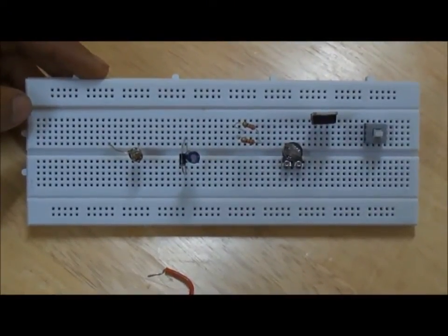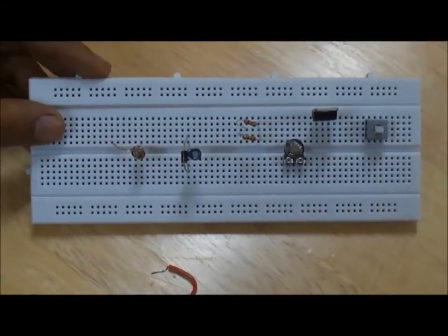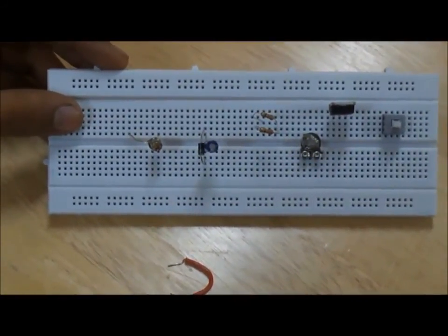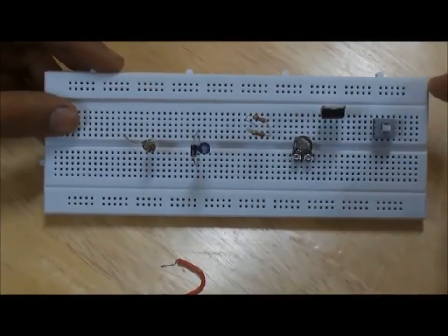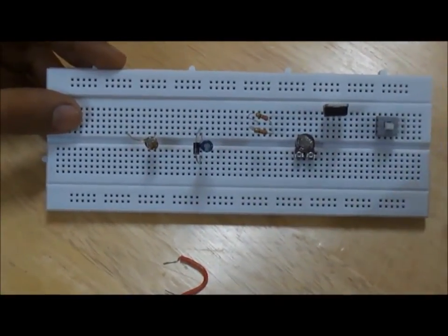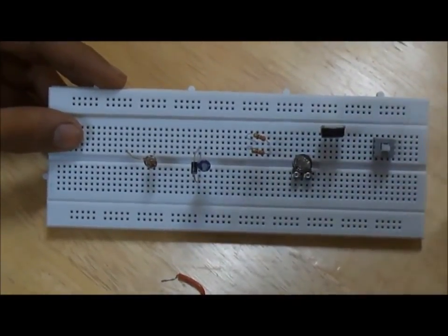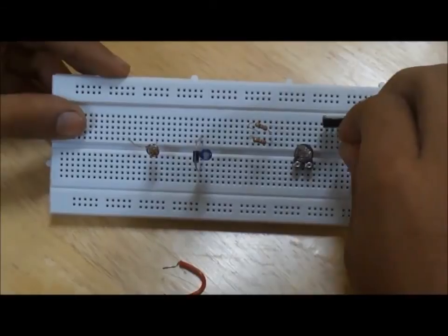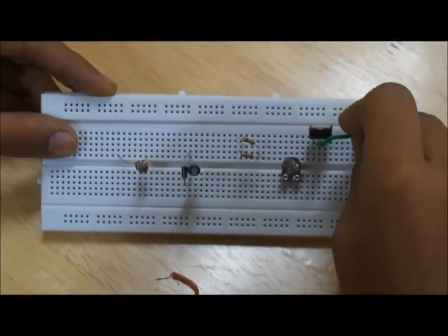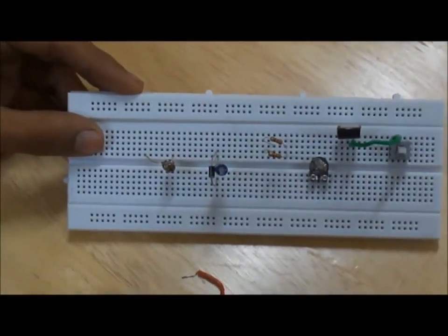We are making the circuit of the laser diode driver. Here we have the breadboard which will act as the base to assemble all the components on the circuit. On the breadboard, in the outer two regions, the holes are connected horizontally, and in the inner two regions, the holes are connected vertically. Now we start with the switch which is connected in series with the LM317 and the positive terminal of the battery.